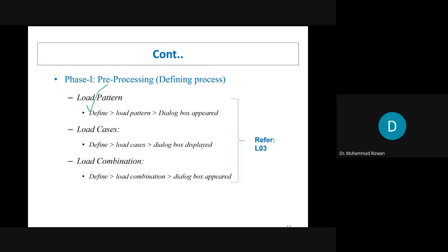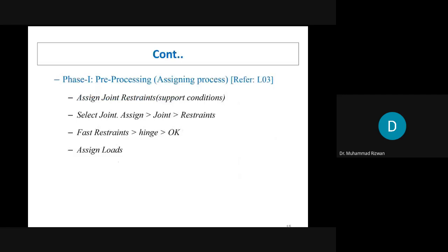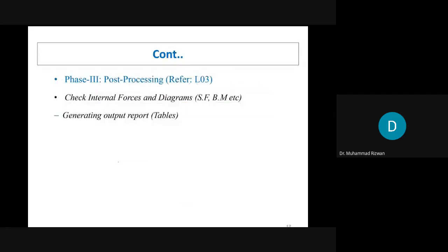After defining, you can define the load pattern, load cases, and load combination. We are already done with this. We are repeating the same steps of the previous lecture as well. The steps remain the same, but depending upon the problem or example, you may have some different steps as well. But typically these general steps will always be there in every problem. Then you can assign supports, run the analysis, and see the internal forces, shear forces, bending moment, or deflection.